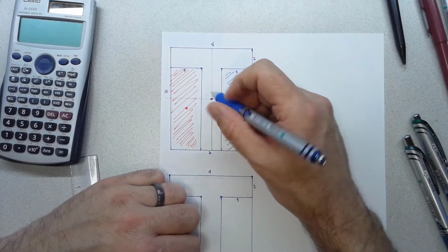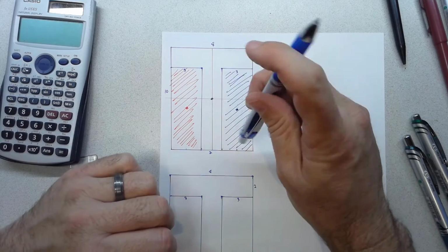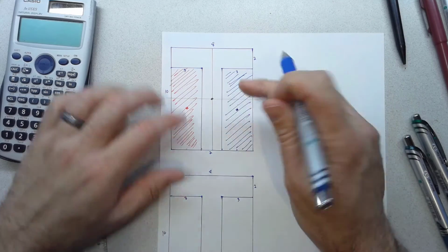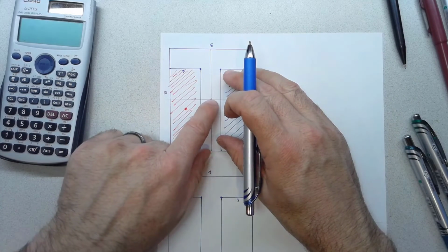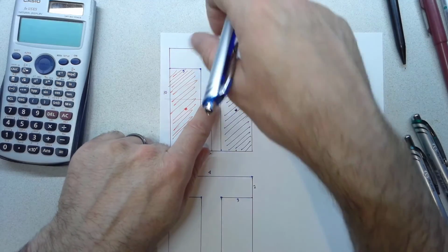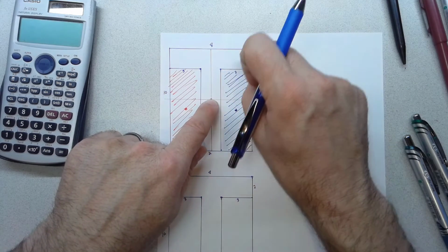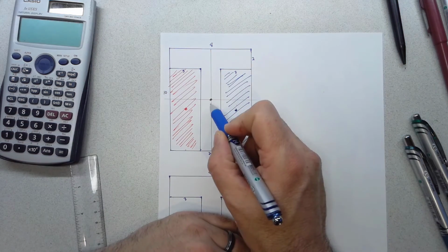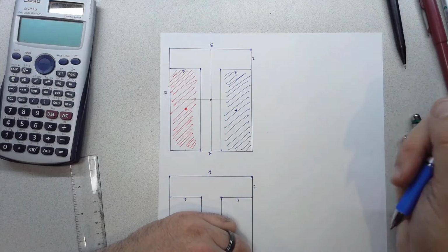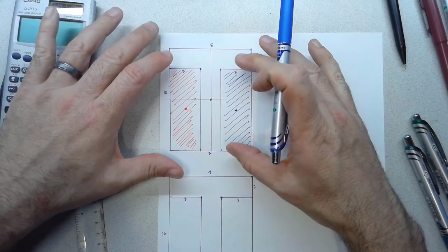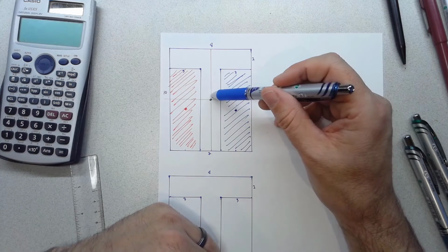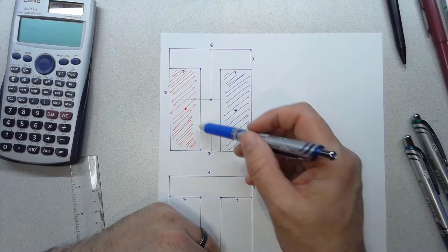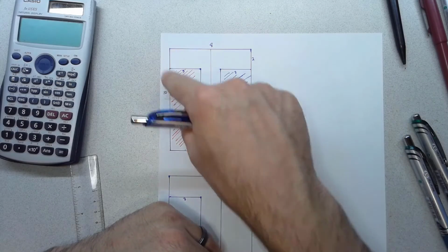You can see that intuitively if you remember what a centroid means: it's a point about which everything balances. When we cut these two away, if we tried to balance it over here, the whole shape's going to tip that way, because we don't have an equivalent area down here to balance it. So our centroid is going to have to shift up. So the first step, anytime we're looking at a composite shape that has a centroid different than the original shape, we have to find where the neutral axis of the final shape is.